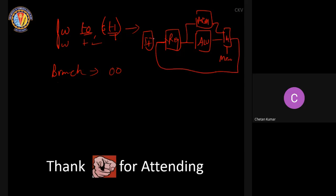Many of you, at least in the papers that I have corrected, have written that there will be no change in the clock period, but there will be a change, because now both of them can act in parallel, since the address calculation for load and store has been entirely removed. Whatever you get from the register content is like an address. You can pass that address directly to the memory. You don't have to pass it through the ALU.